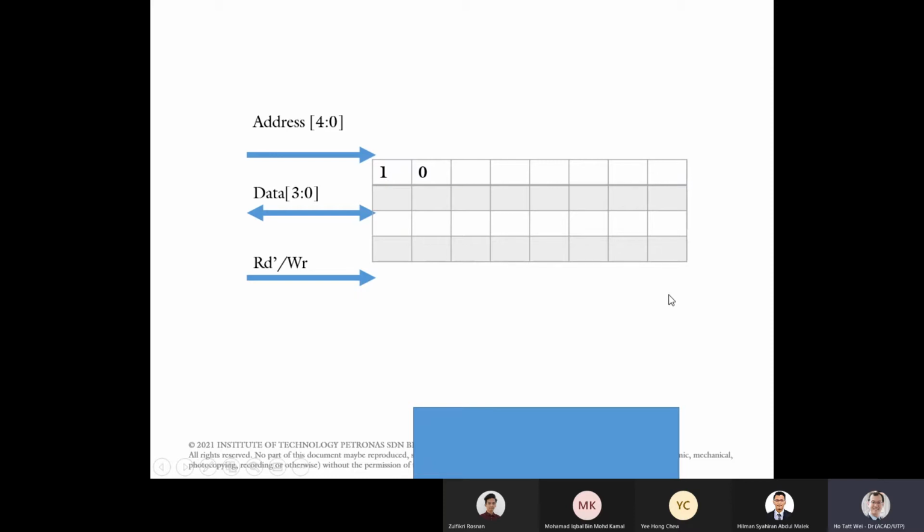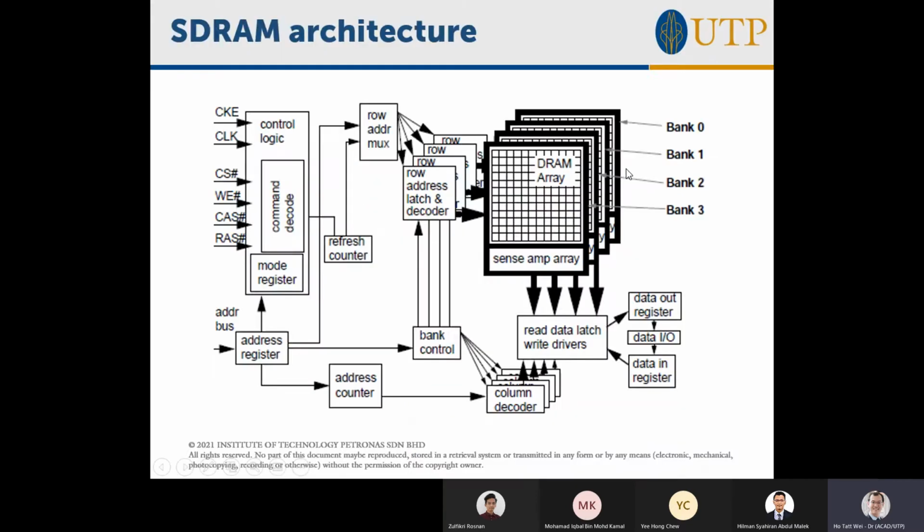So there's some scope for us to actually speed this up, and that is recognizing that it's quite useful. We can just read out a burst of values, bits in sequence like this. And if you remember from computer architecture, you remember your temporal and spatial locality, right? This is spatial locality. Spatial locality is quite important in memory accesses, so you also want to read out in a contiguous fashion anyway, right? So this is what we're recognizing.